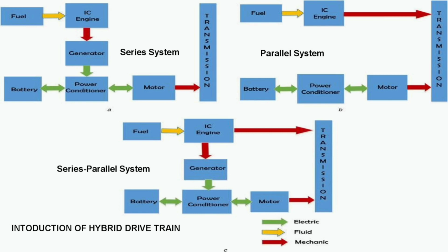So power flow control, hybrid control. The complex hybrid vehicle configurations are 2 types: front hybrid, rear electric, and front hybrid and rear hybrid. Both configurations have 6 modes of operation. Mode 1, during the startup, the required traction power is delivered by the EMs and the engine is in off mode.